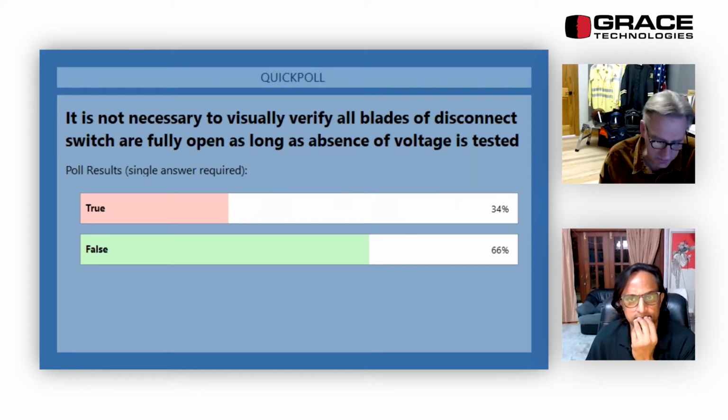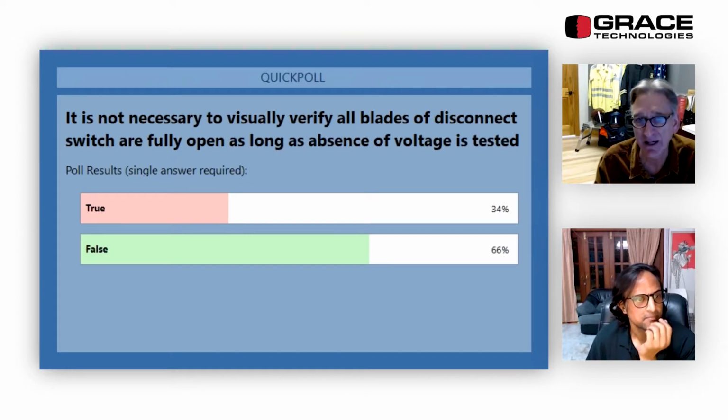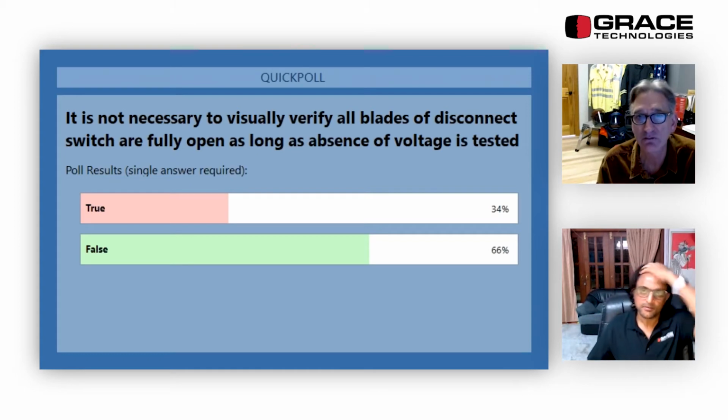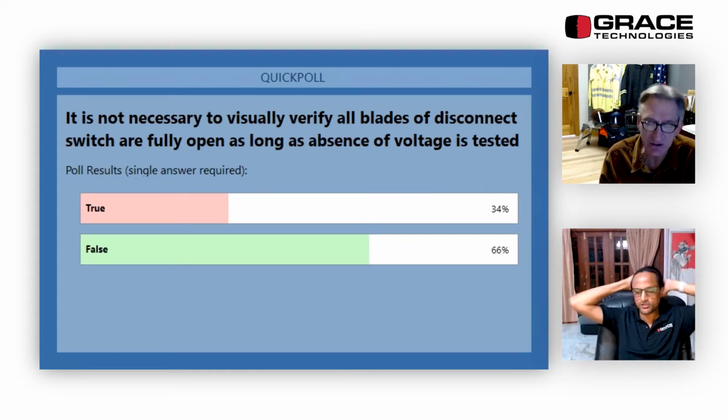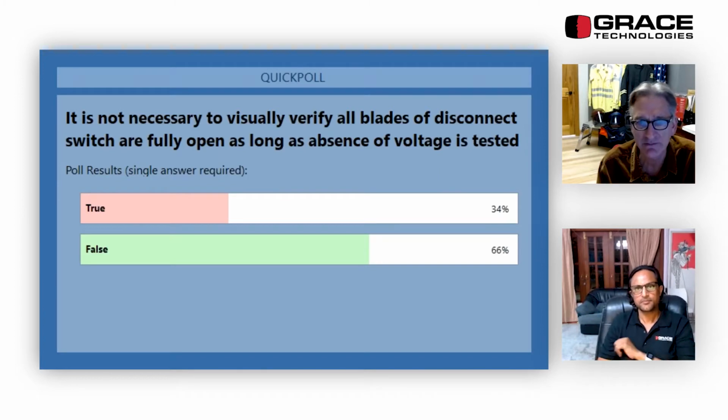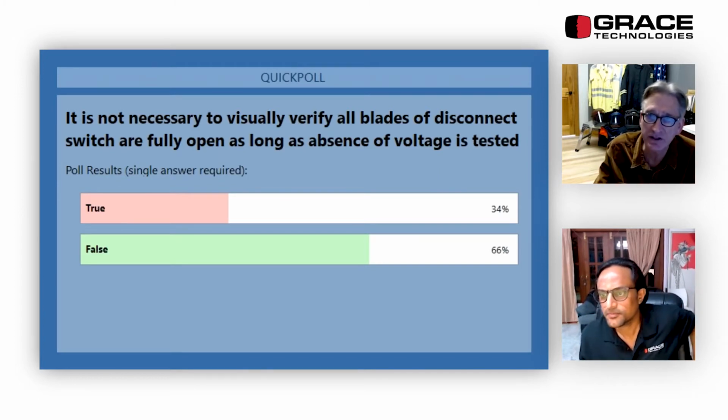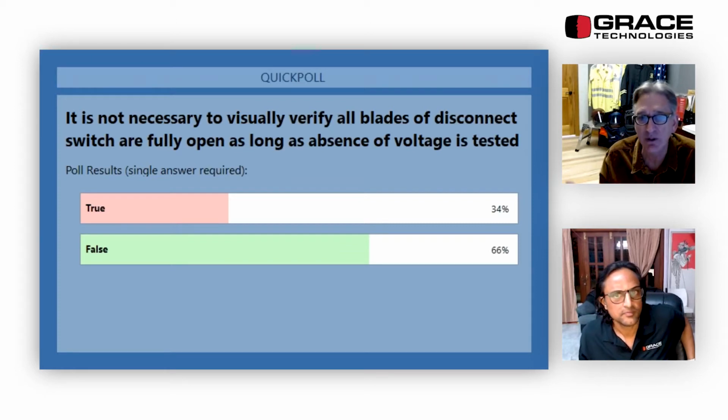All right, so this is from the same section, 120.5, which covers the process of establishing and verifying an electrically safe work condition. I mentioned there are 7 or 8 steps. The reason I keep saying 7 or 8 is because typically step 8 is for over 1,000 volts, because that is installing temporary electrical safety grounds. But we have to do all the steps that are necessary. If it's a 480 volt system, we're probably not going to install temporary electrical safety grounds, so that's going to eliminate step 8.